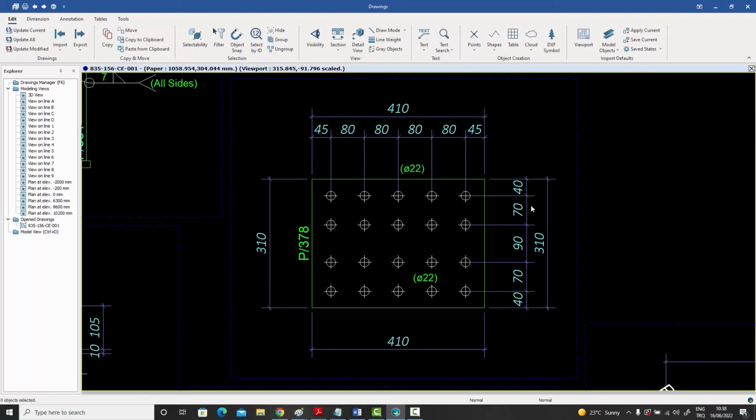Now it's not going to miss any dimensions. It's collecting all the vertical dimensions on the right side and all the horizontal dimensions on the top side, and then it's only giving the totals on the others. But sometimes this might look worse, and you can change that back.